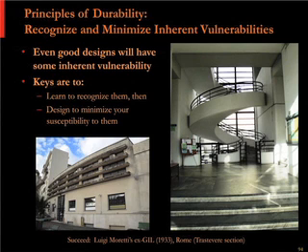And then the consequences, in the upper right photo, if those connections started to fail, the iron corroded and the stone spalled off and that came down, are catastrophic. And for those types of connections, all I've ever seen are bronze dowels. Down near grade, if it's just something you're walking on, I've seen iron. So the Romans really knew where to put the money.